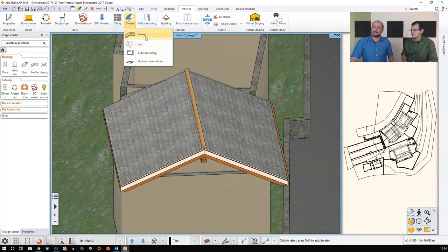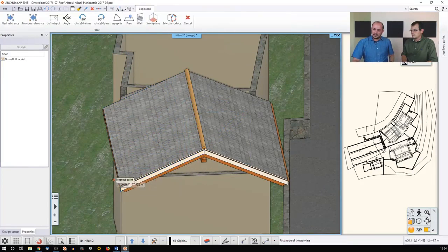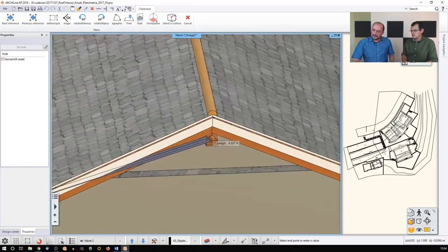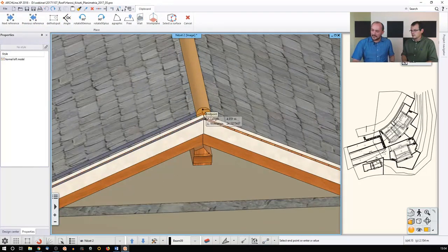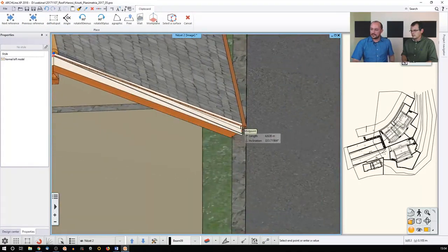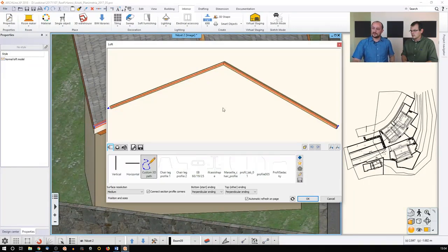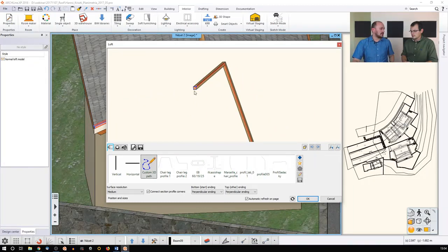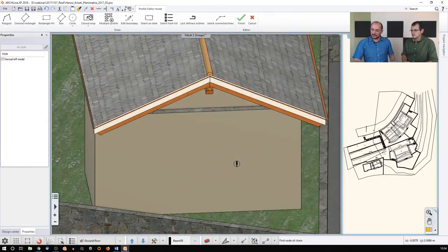It's simply because when you use the sweep tool, you can select a surface, and then you can select edges, and the same thing happens when you are in an interior. You can just find the room contours and the window contour and so on. This way you draft the path. You say, okay, I'm fine with that, but I'm not fine with the cross section. And the cross section is again something that you can set up here. You can select from a range of cross sections, or actually you can create your own cross section.